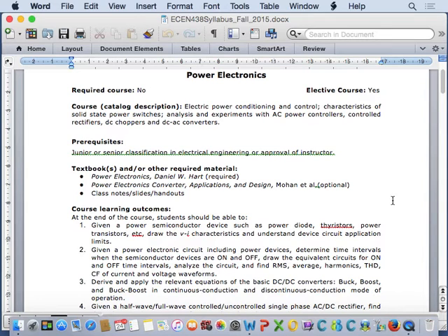Your cell phones, same thing, right? Your cell phones are running off a lithium battery that's probably 3.7 volts. This 3.7 volts is something you're charging sometimes from your USB. Your USB is about a 5 volt DC output, right? So in that case, you are taking 5 volt DC, converting it to what? 3.7 volts or so DC to charge the battery, right?